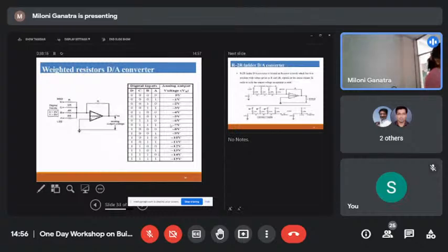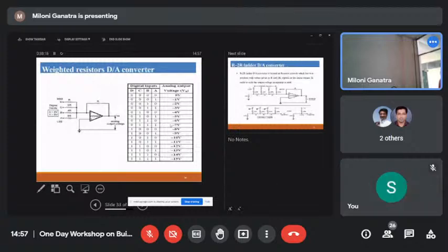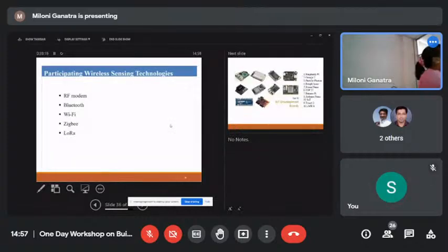For example, LoRa is again something great. This is end-to-end wireless communication, and it is long range. From the name you can understand, long range, but the bandwidth is low. You cannot transmit video and audio, but critical information you can transmit using LoRa. If you go and see YouTube, in Europe they have done up to 100 kilometers of distance. They could send the information. And what is this? It will not need any internet.